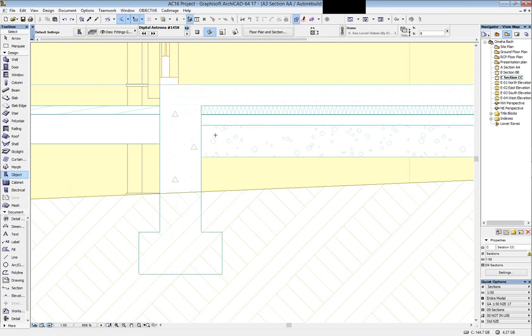If you're not into scheduling, at least we can look at that section and go, well, that's done it for me. I don't have to use 2D overlays. I don't have to use extra lines and fills. So what they're trying to do in ArchiCAD 17 is make the sections more detailed without you doing any extra work. And this is all through the building material priority cleanup.